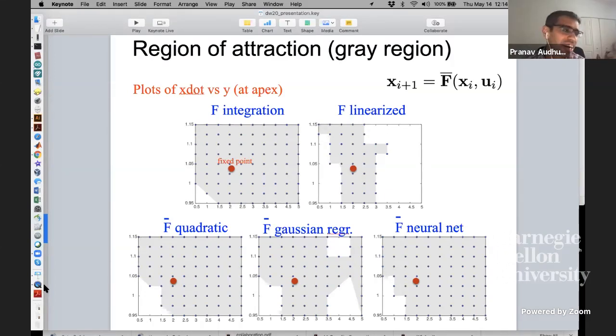I just used the quadratic cost to show one specific example, but you're right. You could just optimize based on basin of attraction. You could take all initial conditions and then say what's the control which minimizes all of them. That's definitely a way. I just showed it as a way to demonstrate that if you keep the cost the same and use a different approximation, then this is what you get. But other ways of finding the control are absolutely valid. Does that answer your question, Andy?